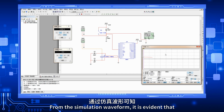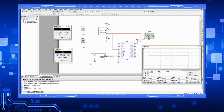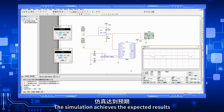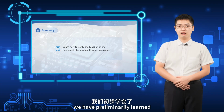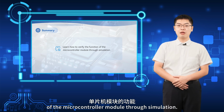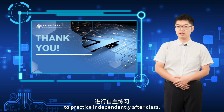From the simulation waveform, it is evident that when S1 is closed, multimeter 1 reads 5 volts. When S1 is open, multimeter 1 reads 3.5 volts. The simulation achieves the expected results and is successful. Through this lesson, we have preliminarily learned how to verify the function of the microcontroller module through simulation. You are encouraged to practice independently after class.